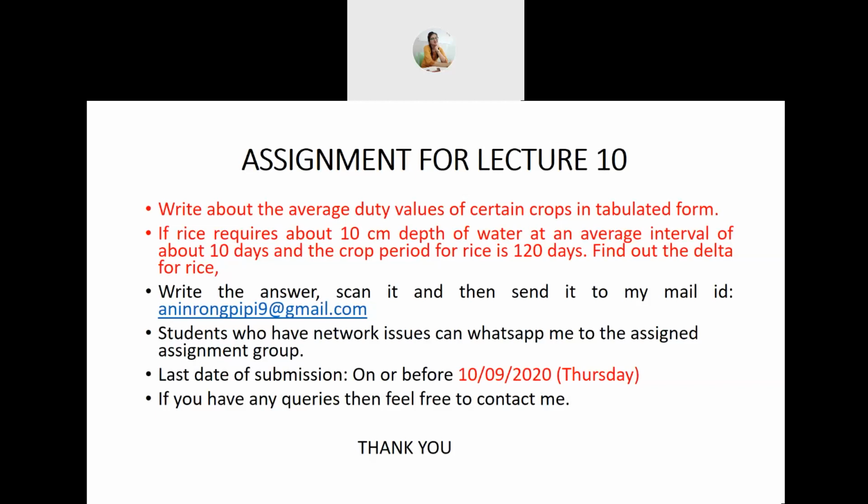So this is your assignment for lecture number 10. I have given you two questions. The first question is, write about the average duty values of certain crops in tabular form. The second question is, if rice requires about 10 cm depth of water at an average interval of about 10 days, and the crop period for rice is 120 days, you have to find out the delta for rice. The last date of submission is on or before 10th of September, which is Thursday.